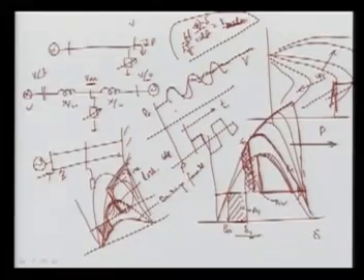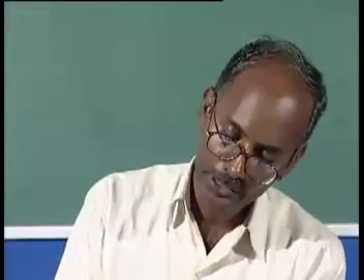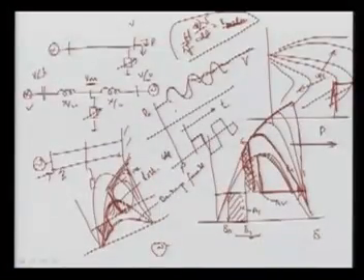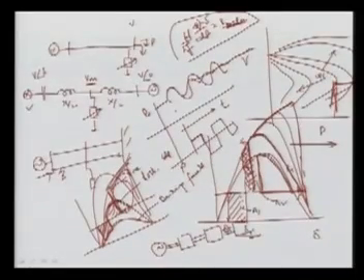Another thing I said is the natural frequency of the system. You know, here we are having the generator. This generator is rotated by the turbine with several stages. So we are having several natural frequencies in these systems. There is a possibility these oscillations will interact with the natural frequency of the system, and huge oscillation will occur, and sometimes it may give chaos and damage to the equipment as well. So for the swings of the disturbed machine, we can put in some reactive power compensation. In this way we can damp out the power system oscillation, and this is another advantage of shunt compensation.